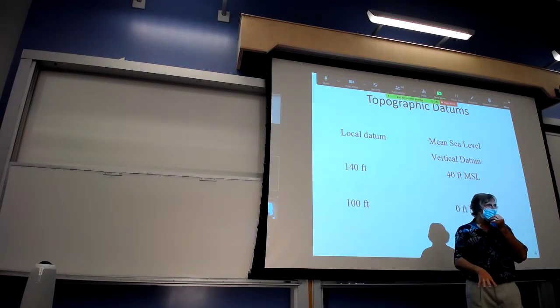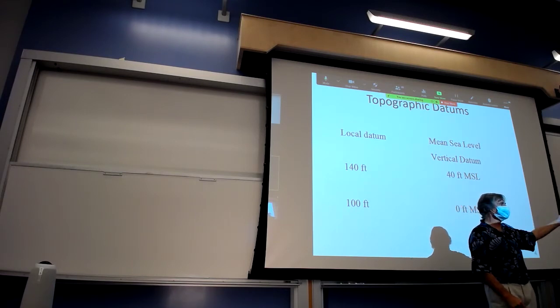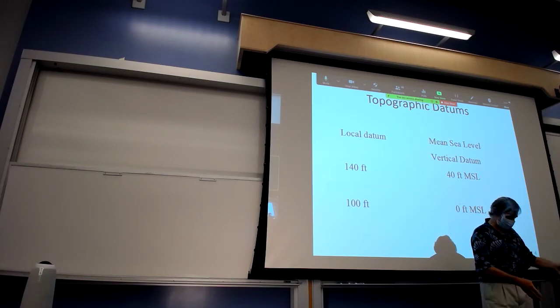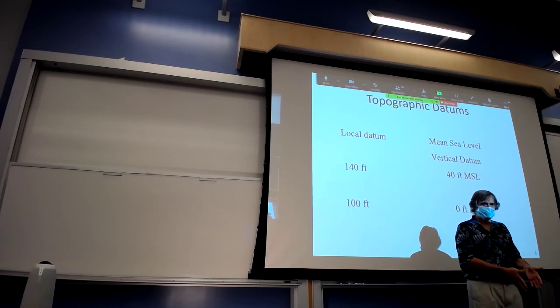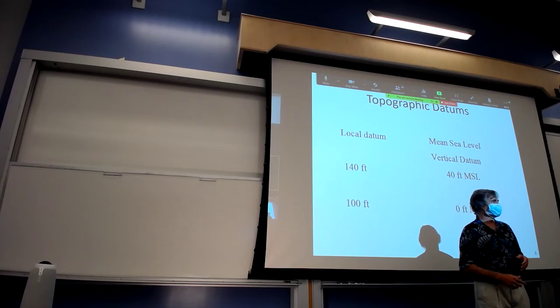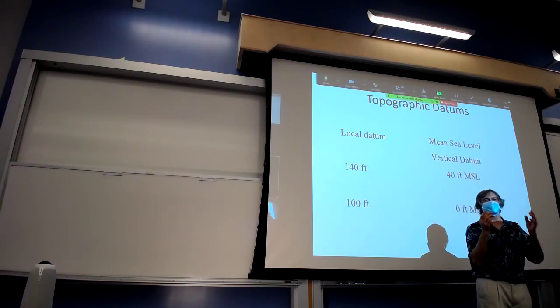If we had a USGS survey marker that was tied to the national datum, and we brought that elevation to this floor, the actual real elevation may be 67.29 feet national datum. And when we surveyed that, we would find that that would be 20 feet higher, but represented in the national datum.